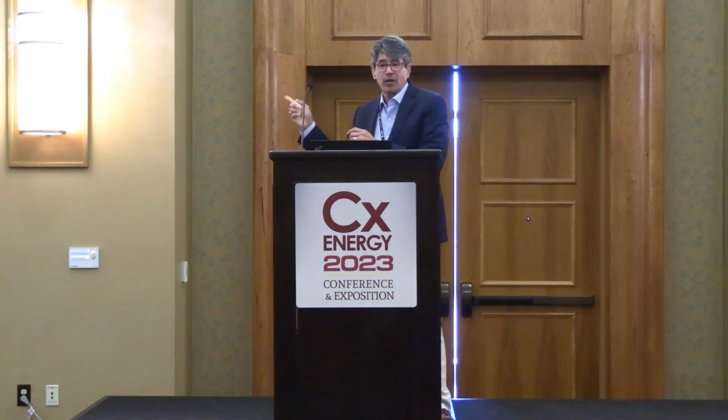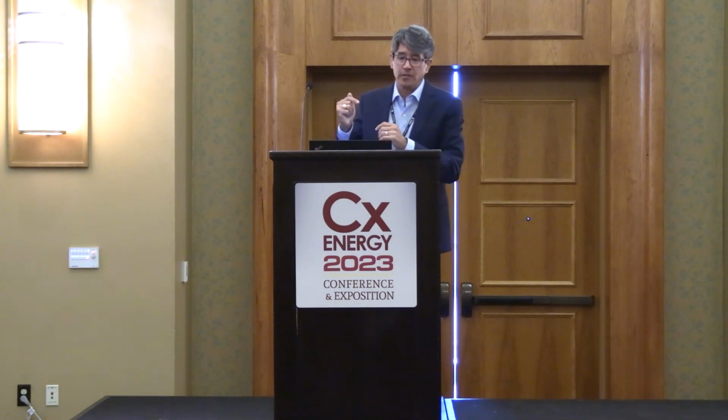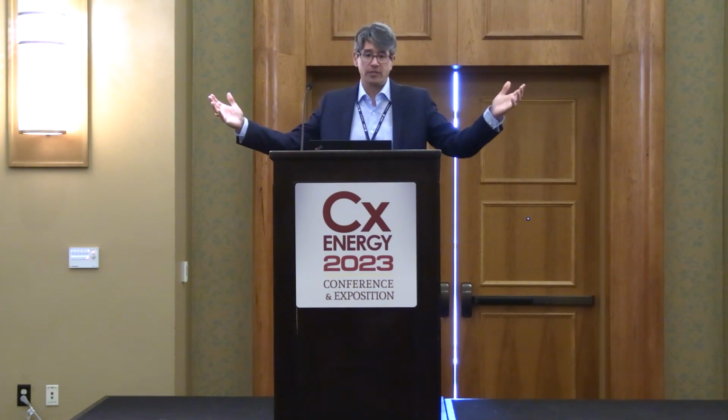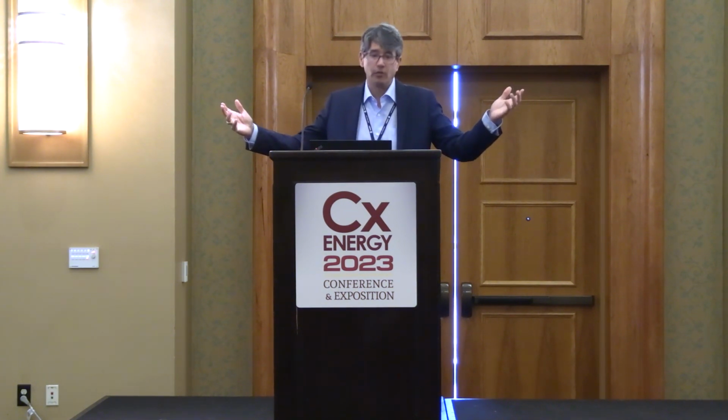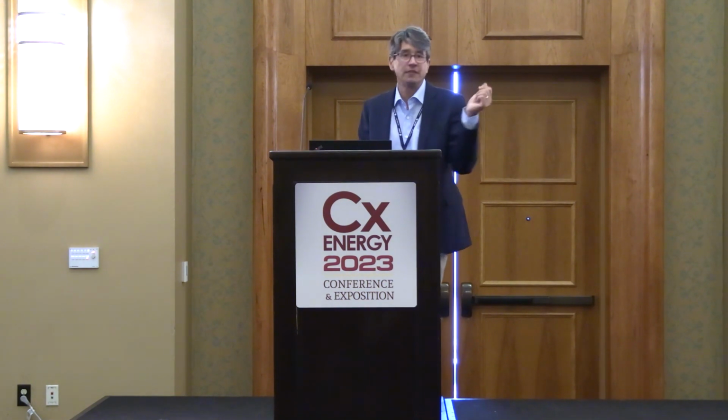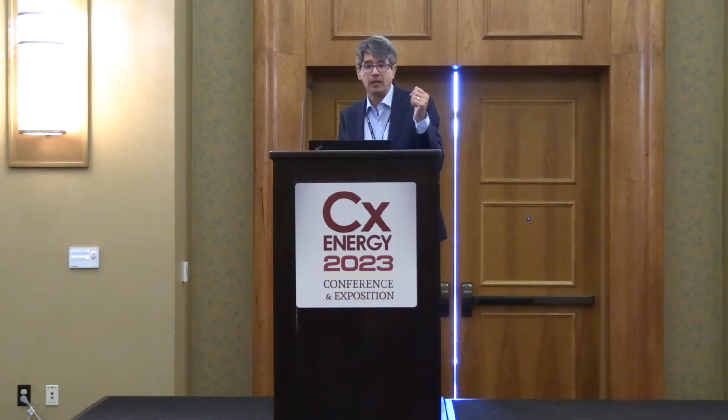Okay. So, ductwork, 30 by 12 ductwork, 10,000 CFM, 2,400 feet per minute. If you're looking at that straight duct, you're going to say, I need to get that equivalent length, and you're looking at 24 feet. So 17 feet downstream, 7 feet upstream.